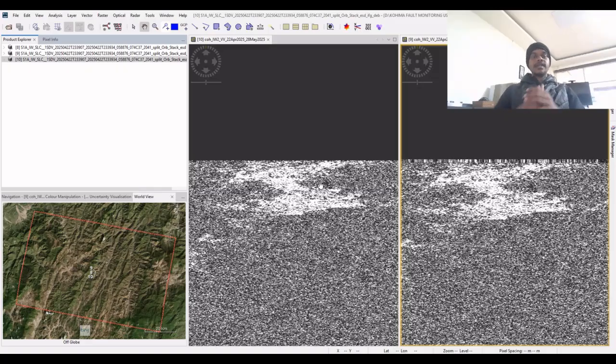Sentinel-1 operates in IW mode using the TOPS acquisition. In this mode, the satellite does not record one continuous image. It has subswaths like IW1, IW2 and IW3, and the bursts slightly overlap with each other. This allows wide coverage, but creates visible burst boundaries in the data.